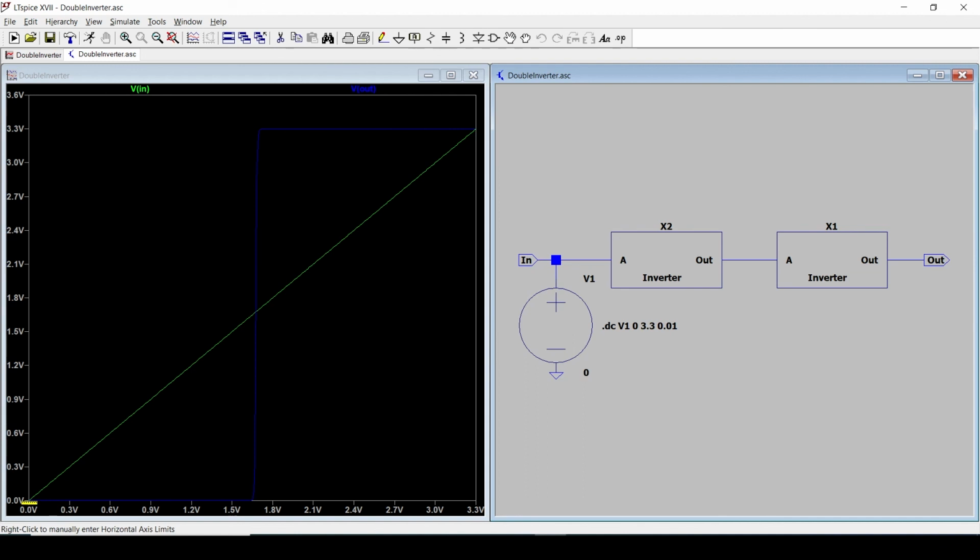So that brings us over here. And so very quickly we end up either down here, or if we're up over here, if the input's at 2.4 volts, then that means that the output is going to be very close to 3.3 volts, which brings us down here. And so very quickly we end up at this corner here.